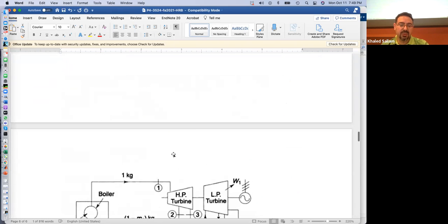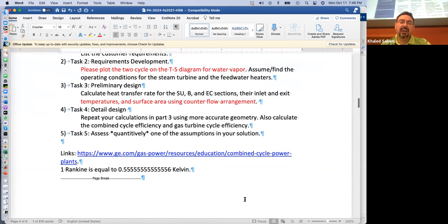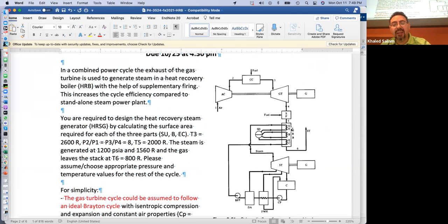But it's super nice that you have the whole code simulate this. So finally, it seemed that we need m dot steam and we need m dot air. So actually what we really need is not both of them, we just need the ratio between the two of them so that we can calculate the cycle efficiency.